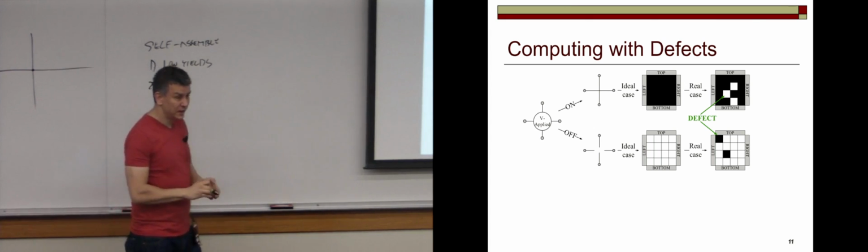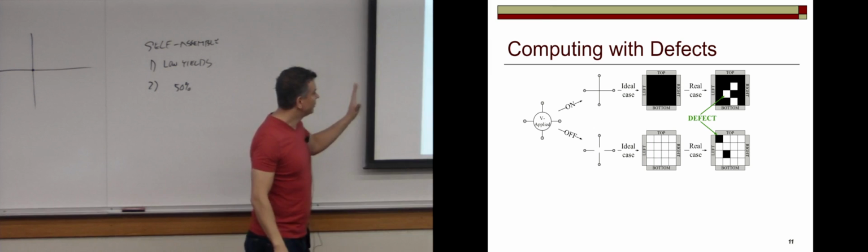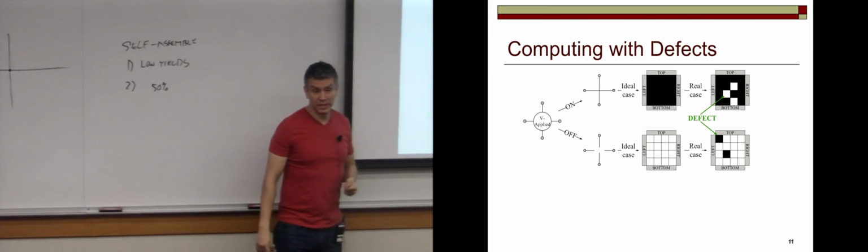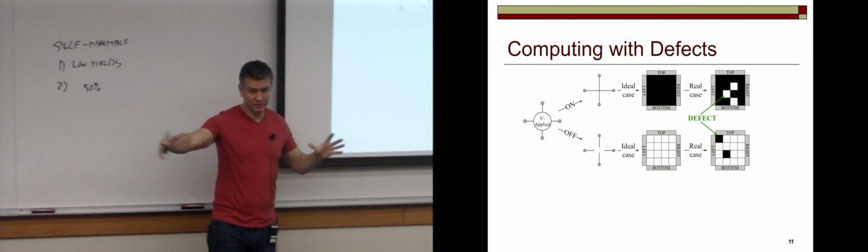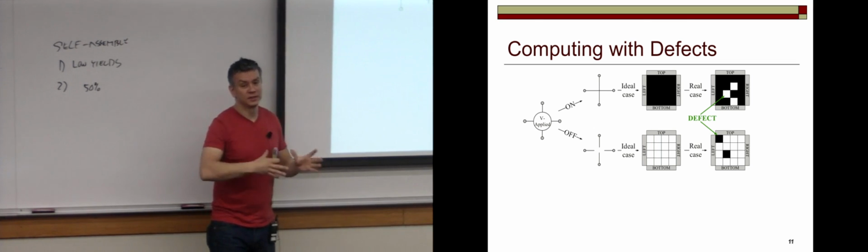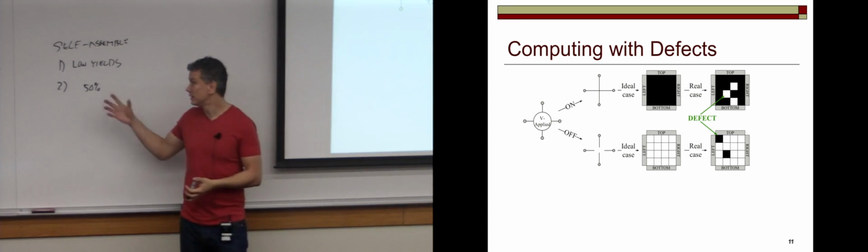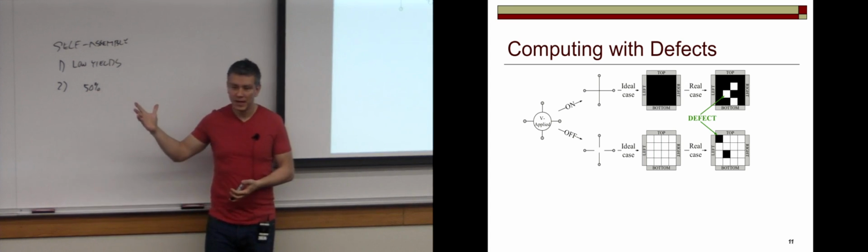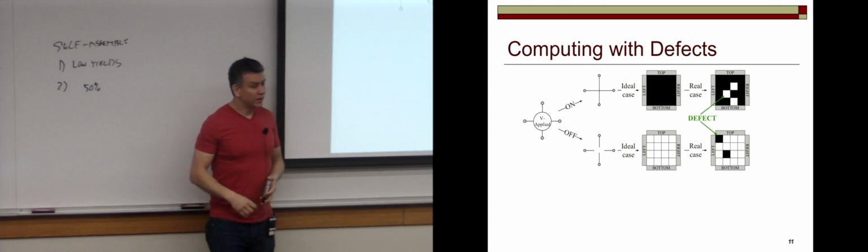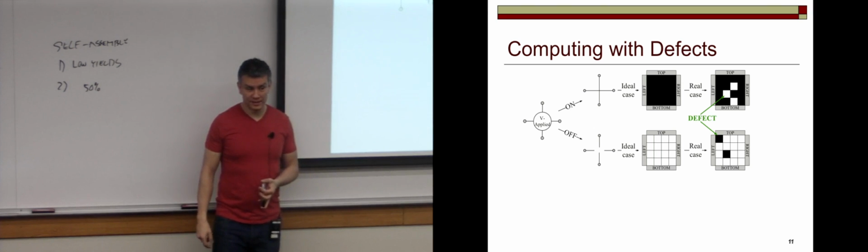So even those that they don't reject will have perhaps 50% of the switches being defective. So they create a vast array of wires and switches, incredibly dense, incredibly exciting, but full of defects. And they simply state, oh, but since we have so much redundancy, since we have so many such switches, we'll just figure out at the logic level how to cope with these defects.